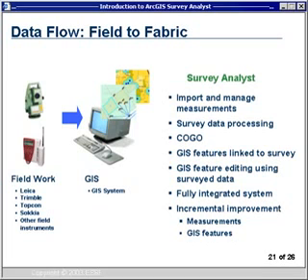It also supports the coordinate geometry function that we talked about for entering the measurements into this database. And once again, this COGO that we're talking about here is used to enter those measurements into the measurement database. From the measurement database, you do computations and resolve features in a GIS layer. And I'll show you an example of that during the demonstration.